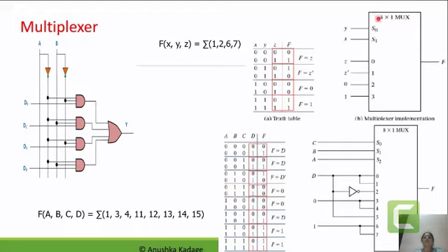And this is how the input we have to choose is either z, z dash, 0 or 1. And that's why for the input lines the values will be z, z dash, 0 or 1. And out of these 4 values, any one of the values will be presented as f for this 4:1 mux implementation block.